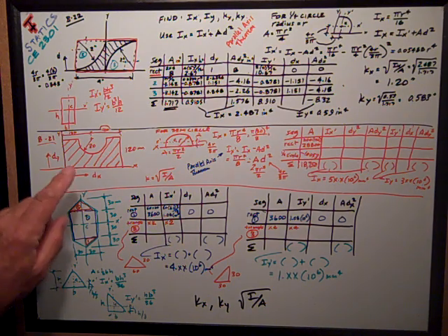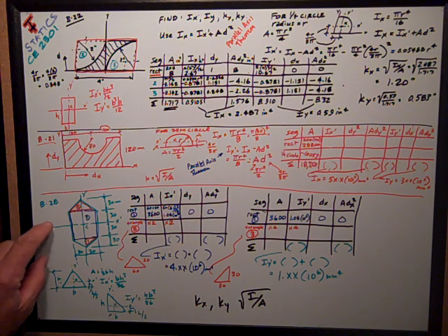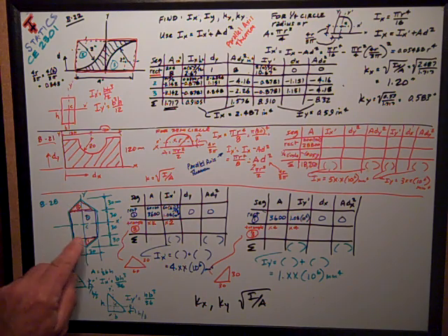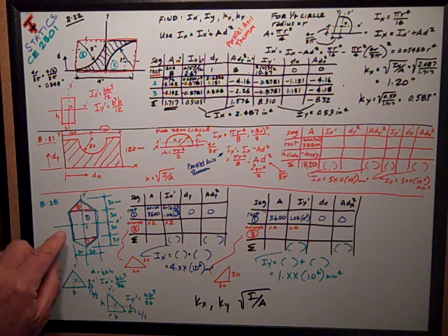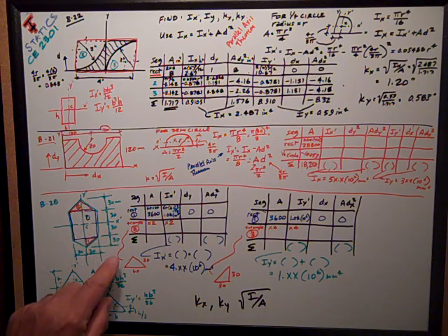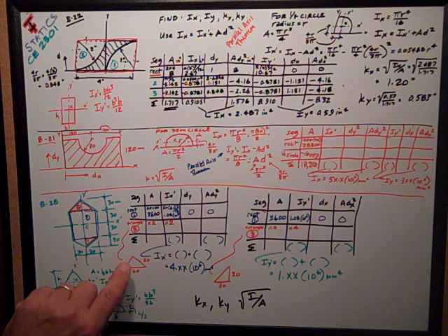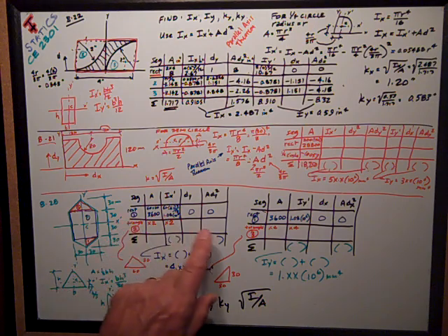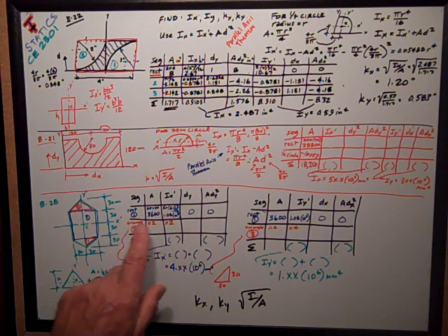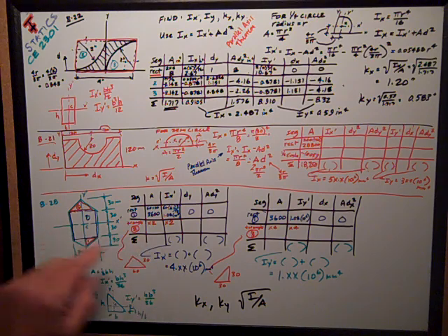Okay, now we finally get away from these semicircles and quarter circles, which are hard, and I get this sort of 6-sided figure. These dimensions are 30, 30, 30, 30, 30, 30 wide. Break it up into 3 segments. Break it up really into 2 segments to do Ix.